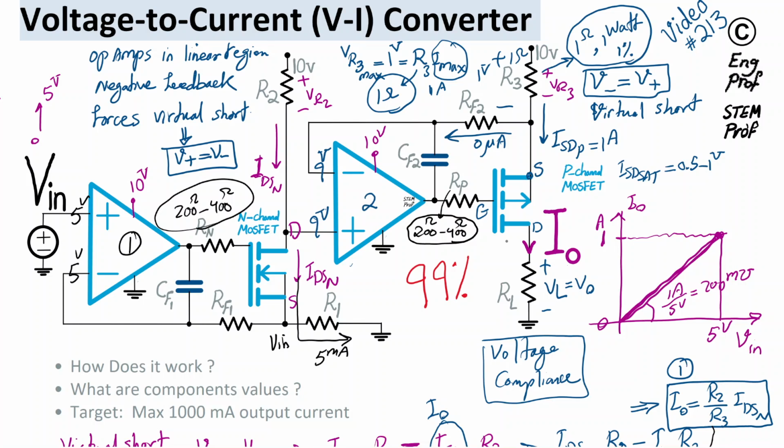But when we select them, then based on that, we can play with the value of the resistor Rp for stability in the circuit, to make sure the circuit is stable, with no oscillation, no weird behavior, no ringing. And the same thing for Rn, we select the value properly, except that the NMOS or N-channel MOSFET here carries very low current, so there are many choices for that one.